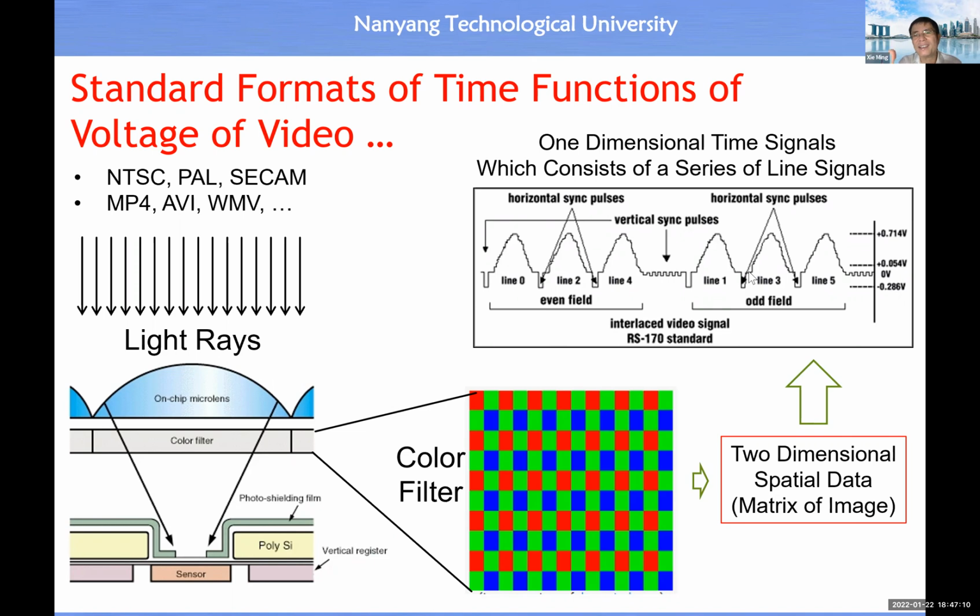And this is just for you to know: when we shift out the image row by row, we package them differently. Row 0, row 2, row 4 come out as the first half of the image. Then the second half is rows 1, 3, 5. So you have an even field and an odd field.